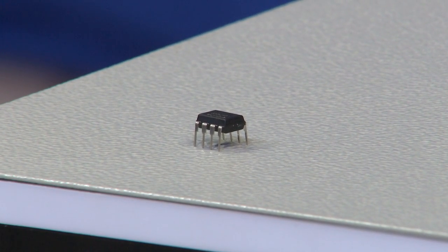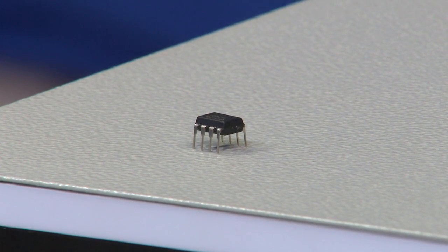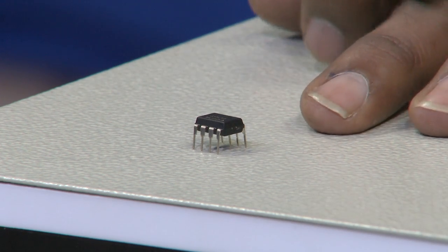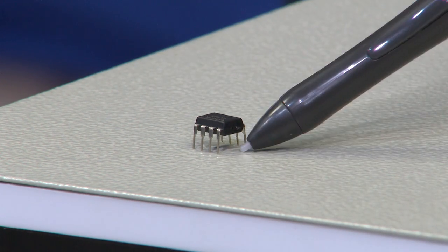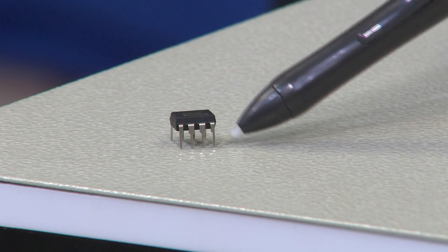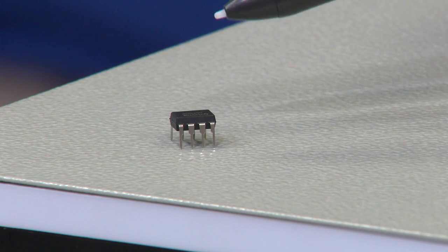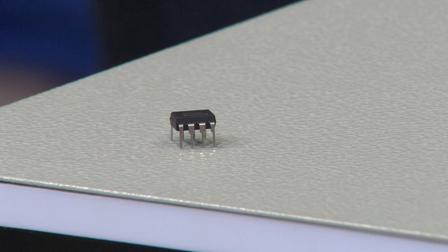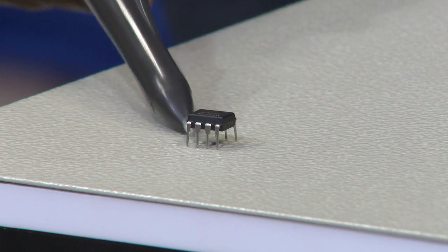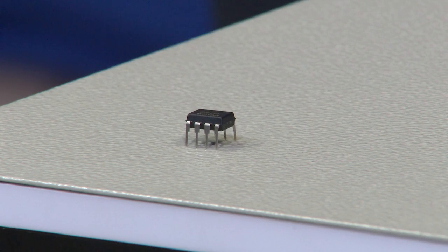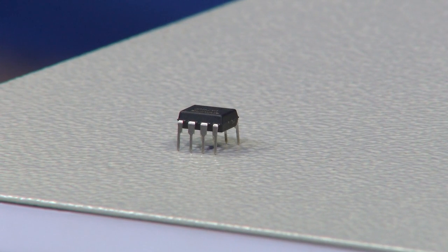In the same way, the output impedance for an ideal op amp would be 0, but in the practical operational amplifier you will see that the output impedance is not 0, but close to 0. Then the gain: in this practical operational amplifier the gain will not be infinite, that we will see today. So, let us see one by one.